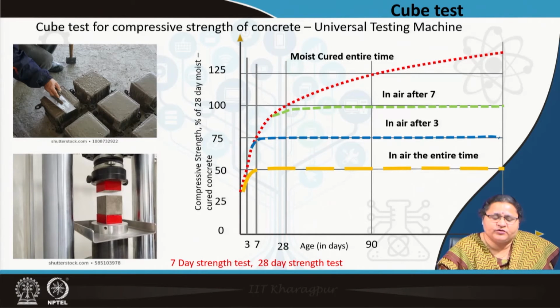casting. So you have taken samples for testing. Now what to do? On the next day you can demold it, those are inside molds. These molds are of 3-inch mold, 4-inch mold, 6-inch mold, it can be circular mold. These are usually cube like, circular is obviously cylindrical, and at least 6 to 12 such cubes are taken.